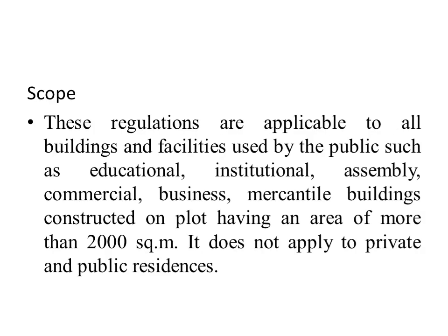Today we are going to see what are the special provisions in certain buildings. So in this slide we are going to see why there is need to go for special provisions for the building. These regulations are applicable to all buildings and facilities used by the public such as educational, institutional, assembly, commercial, business, mercantile buildings constructed on plot having an area of more than 2000 square meter. It does not apply to private and public residences.